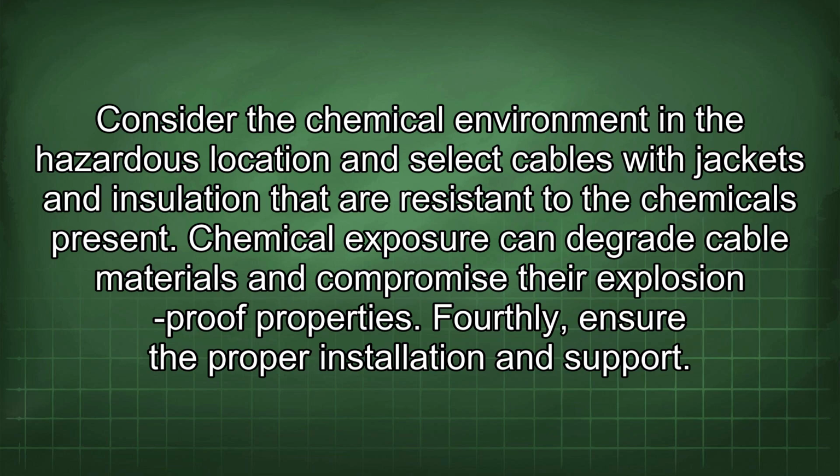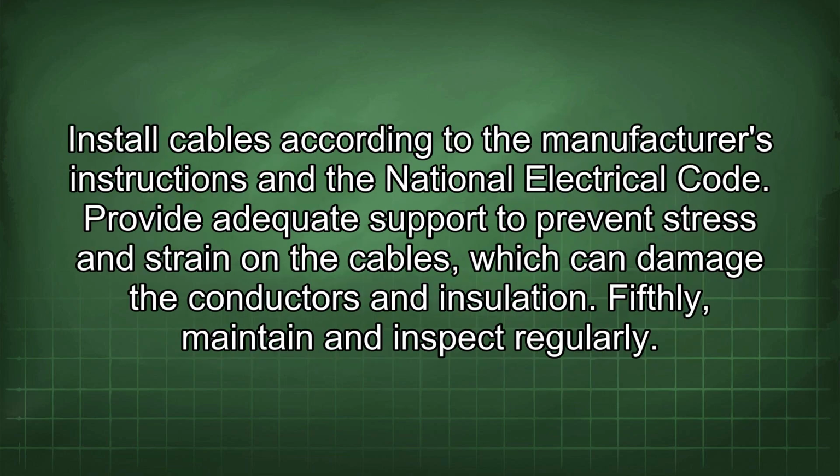Fourthly, ensure the proper installation and support. Install cables according to the manufacturer's instructions and the National Electrical Code. Provide adequate support to prevent stress and strain on the cables, which can damage the conductors and insulation.